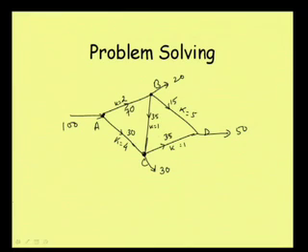Then 30 plus 35 must be equal to the 30 going out from this point and the 35 going out from this node. So now it is satisfying all the conditions. Let us verify if our assumptions are correct. 15 is coming from this point, 35 is going, so 15 plus 35 is equal to 50, and finally 50 is going out from this point. So that way, we have put the first approximation of the discharge.